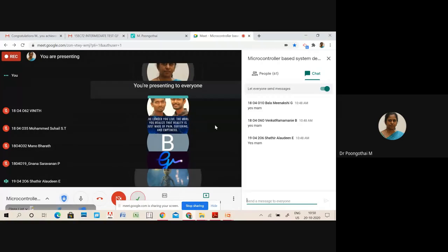After initializing all your initial values, you have to monitor your RI flag, whether the data byte is received or not. If the SBUF is full, it means the data byte is received, so your RI is set to 1. That means the data byte is available in your SBUF register. Now we have to clear the RI flag and move the data from SBUF to the corresponding port.